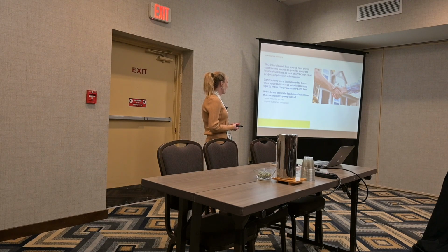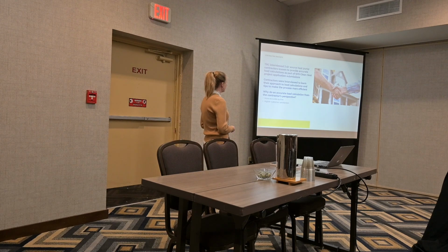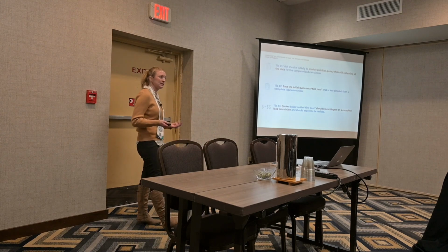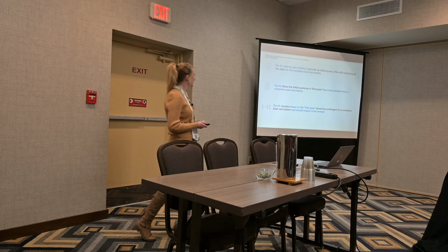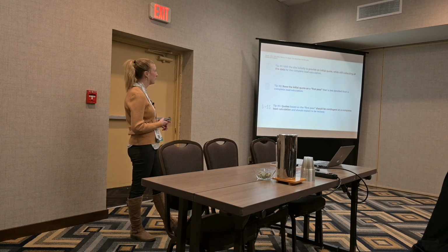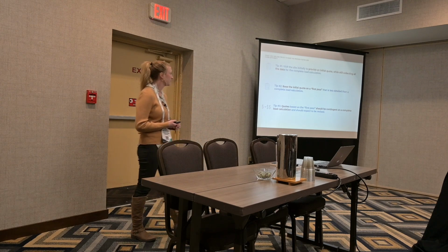The main reason they said that they take the time to do an accurate load calculation is because it produces more accurate quotes and it leads to higher customer satisfaction. We also asked them for some tips to make the process quicker while still producing an accurate load calc. Tip number 1, they said, visit the site initially to provide an initial quote while still collecting all the data for the complete load calculation.